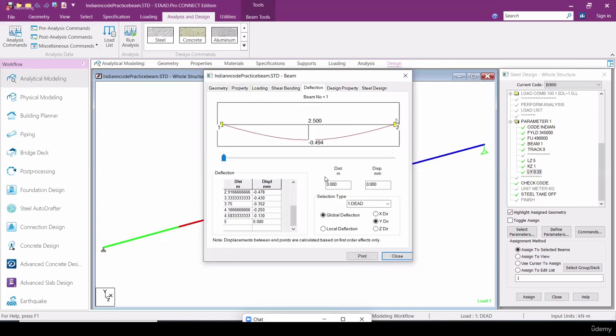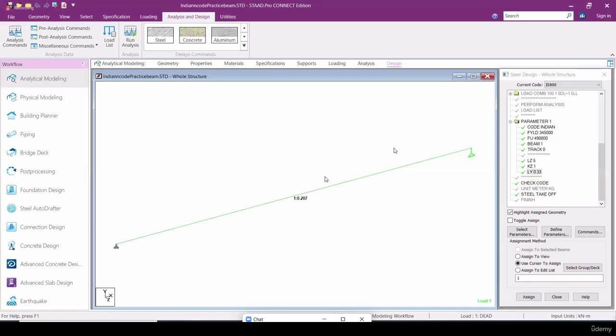There are certain deflection limits, and I'll show you all these limits wherever they are. Generally, since our example is a mezzanine joist, this will be checked for 360 for live load, and 240 for both dead load and live load. How these will be taken, I'll tell you all these things.